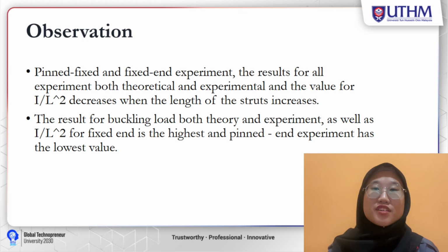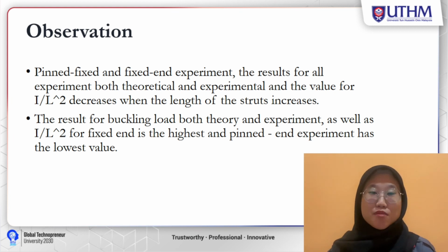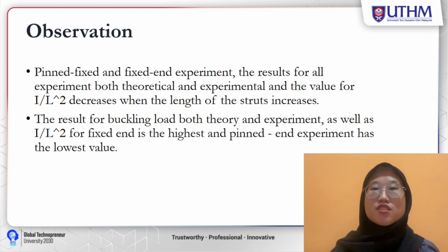So the observation, based on the results from the pin-pin, pin-fixed, and fixed-fixed experiments: for all experiments, both theoretical and experimental, the value of I over L squared decreases when the length of the strut increases. From the results, we can also see that the buckling load, both theory and experiment, as well as I over L squared, for fixed-fixed is the highest, and pin-pin has the lowest value.